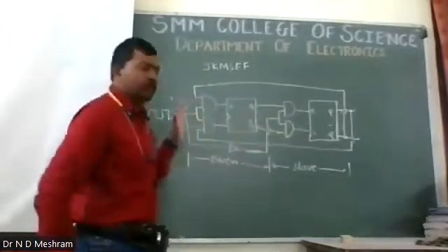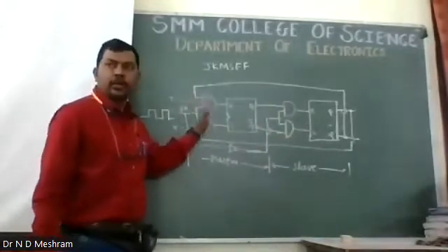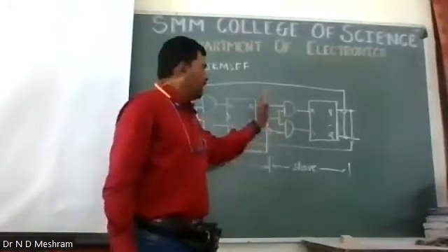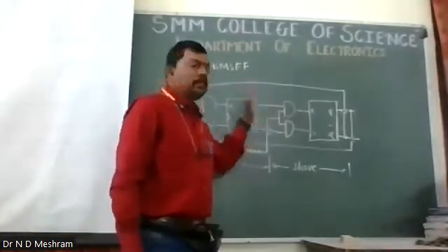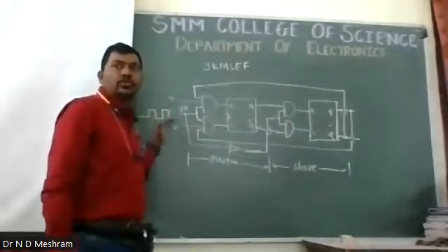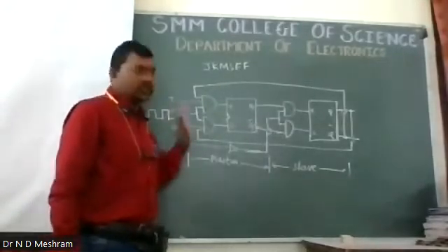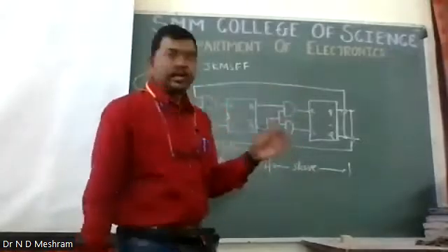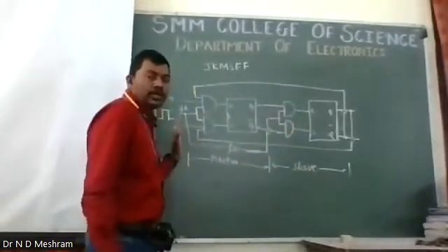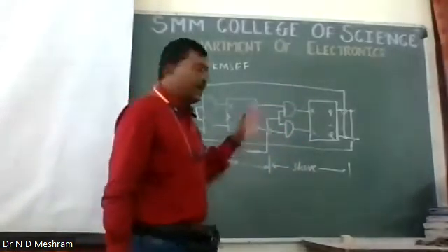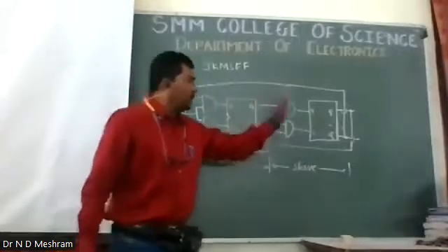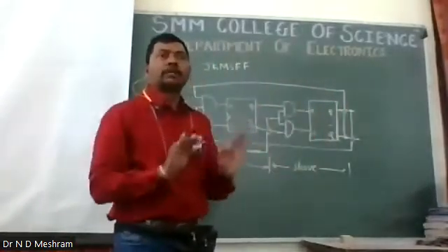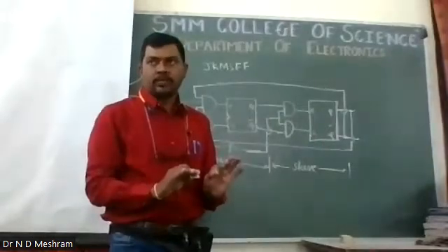Up till then, what will happen? The output which is fed over here comes across this first master flip-flop, and it remains here until the clock changes to low, right? So this JK master-slave flip-flop works on the falling edge. As soon as the clock input goes low, the output from here transfers to the output. The rest of the truth table remains the same as we have studied.